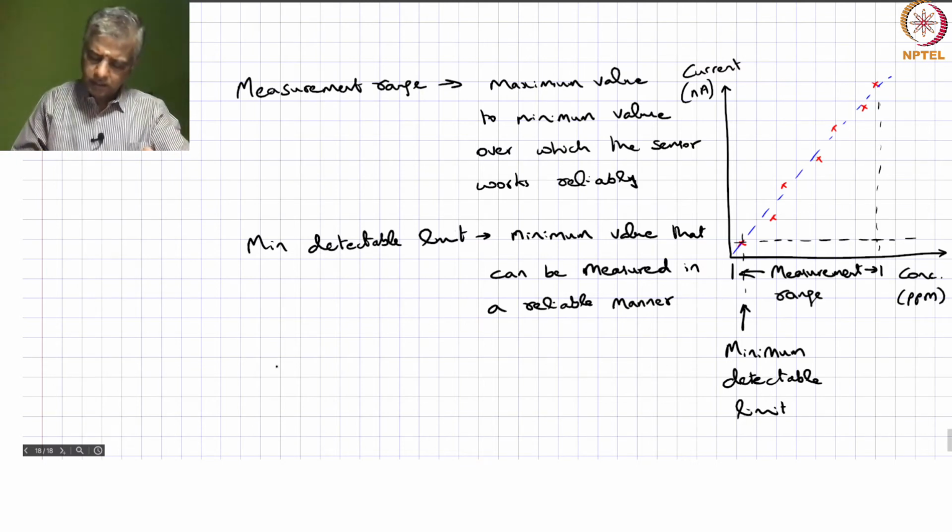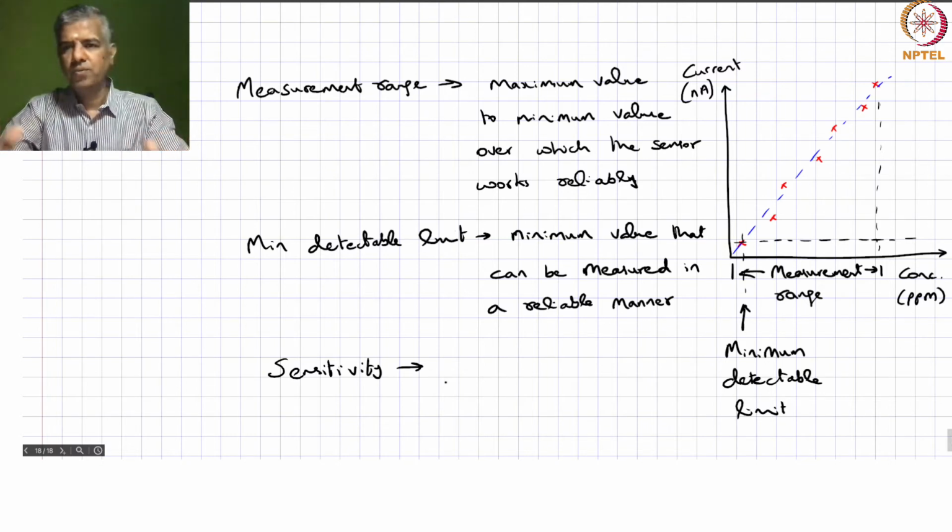Then there is sensitivity. And in terms of the usage of that word, sometimes it may be a little confusing, because when we say sensitivity from an optical communications perspective, people are talking about the minimum power level that should be incident on the receiver so that you can maintain a certain bit error rate in a digital communication system, right?